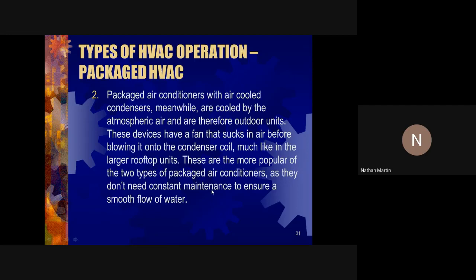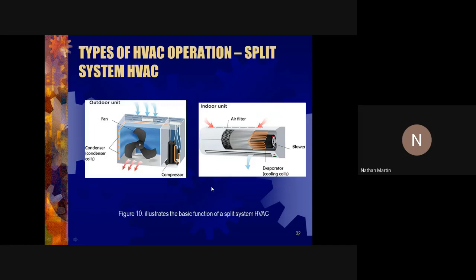However, if they are not maintained properly, because they are sucking the air directly and pushing it into the space over the cooling coils, then they have to be maintained on a much more regular basis, meaning you have to take out the filter and clean it. Sometimes you have to wash down the outside part of the unit, the part that is showing outside. That is why a lot of times these units tend to not cool and break down, because of lack of servicing, right?